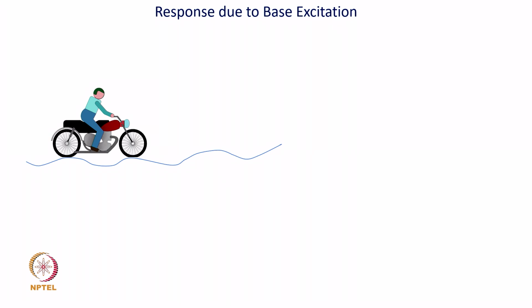response phenomenon. Till now what we have done is, suppose this is our vibratory system, then we said that this entire chassis of the vehicle is like a mass, and we modeled the suspension using this spring dashpot system, and maybe this engine is creating excitation force. The engine has a crankshaft and the IC engine is spinning with some speed, and that is going to create an excitation source for the chassis to vibrate.